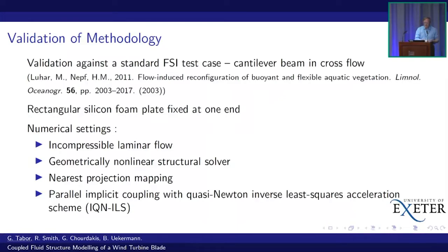The experiment uses a rectangular silicone foam plate fixed at one end. It's fairly floppy, so you'll get a reasonable amount of displacement here, using incompressible laminar flow, and a non-linear structural solver on the CalculiX side, and coupling using nearest projection mapping and IQN-ILS coupling there.